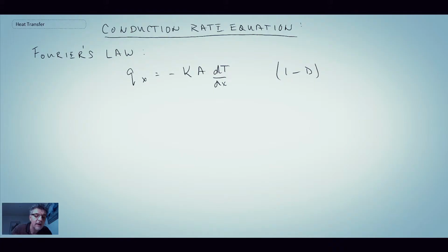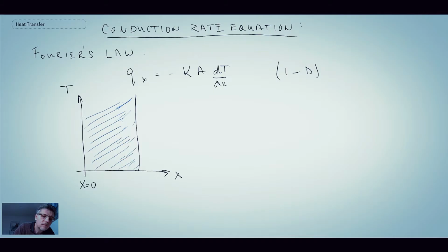So what we're going to begin by looking at in this equation, we're going to write out a little schematic showing the temperature with the distance in a solid. So let's assume that we have some solid and we have temperature, and then we plot distance along the horizontal. If we could measure the temperature, let's say we measure T1 here, and then a little further into the solid we measure T2. And what we find is for one-dimensional conduction, oops, I didn't do a very good job of that, this should be a linear line, a straight line.